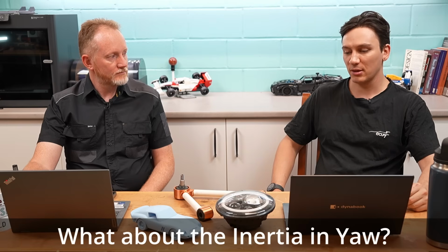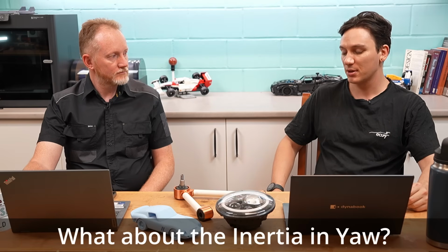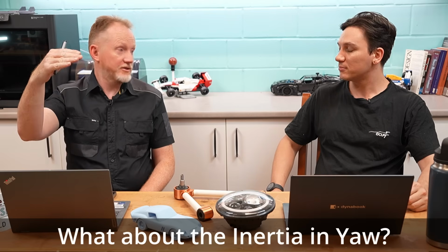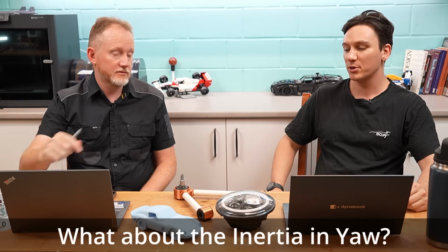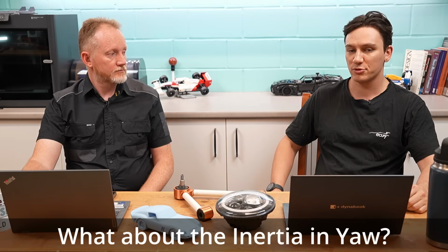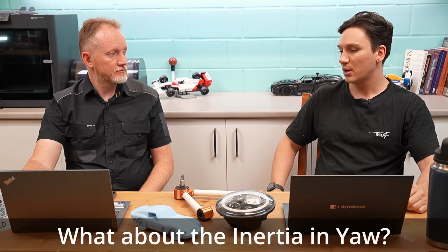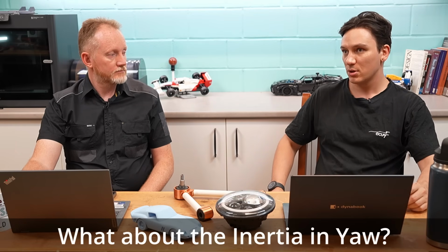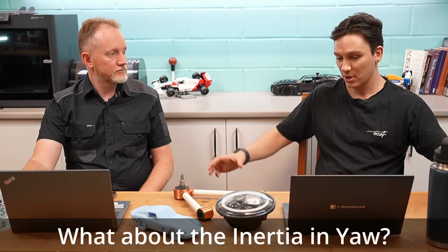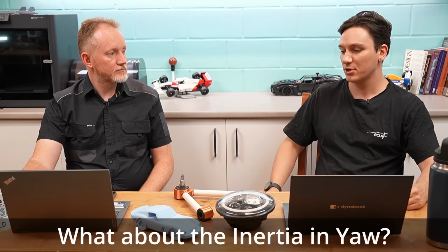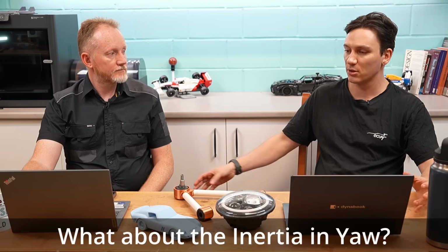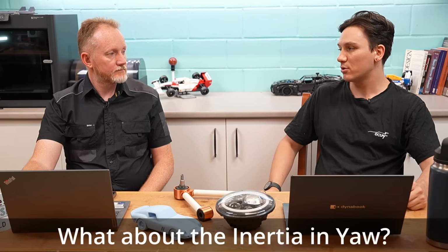I think low mass is probably the top of the list for me. If you've got low mass, you're going to have low inertia anyway. In a car that has low mass, you're going to struggle to place huge mass outside the center of your car. So you're going to have that low polar moment of inertia in any case. You mentioned the engine; it's fairly close to the driver's back.